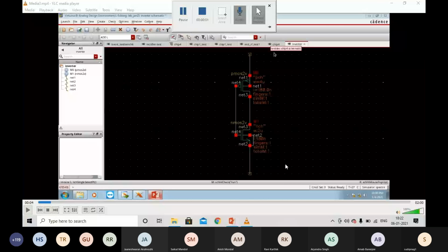So it is better if you draw a symbol, something like the symbol of a NOT gate, and whenever you instantiate or use that symbol, that means there are 2 transistors and these connections inside that particular symbol in a hidden form. So the performance of the NOT gate symbol will be the same as the performance of this exact circuit with this selection of transistors and their properties.